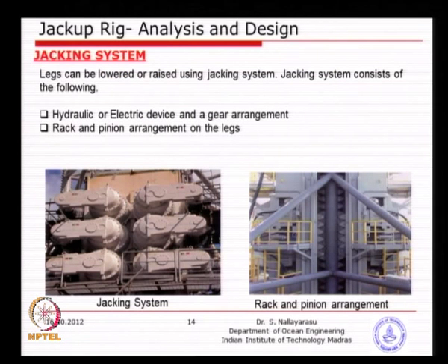The next thing that we need to learn about is the jacking system, how these things work, how the jackup legs are going to be moved up and down, vice versa, how the hull is going to be moved up and down with respect to a given reference plane. So, you see here the jacking system consists of first the mechanical gear arrangement with electrical devices mostly, sometimes you do have hydraulic devices, and then the rack and pinion arrangement, one attached to the structure side, the other one on the machine side.